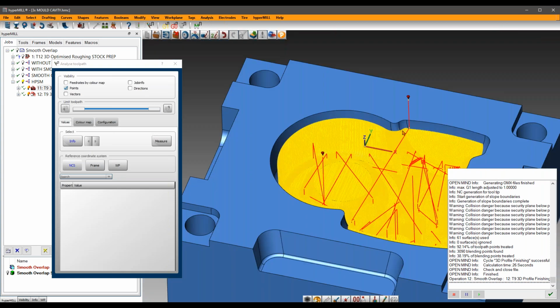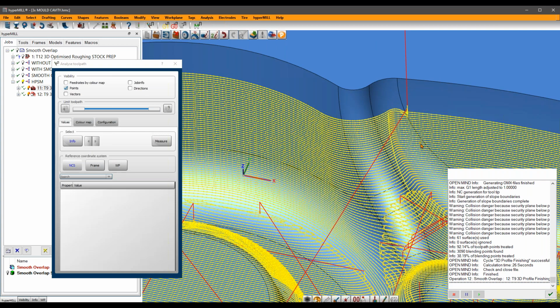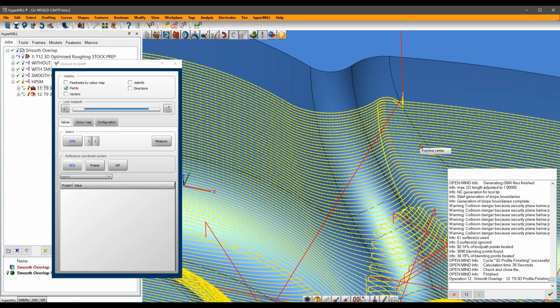So we can go so far with the machine tolerance. Currently, I'm set to 5 micron machining tolerance with high precision surface mode. You can go sub-micron. If you've got a super dynamic machine, the latest Heidenhain controllers, they're good for 5 decimal places.